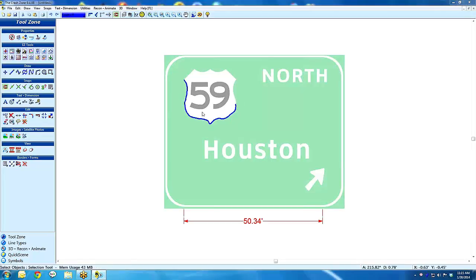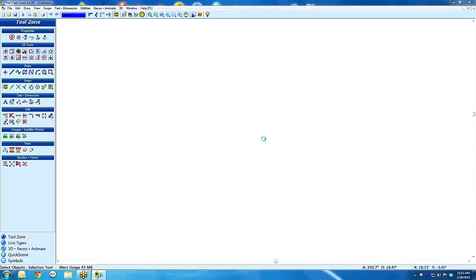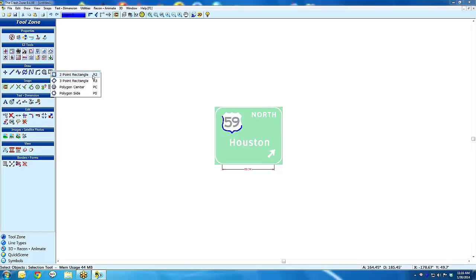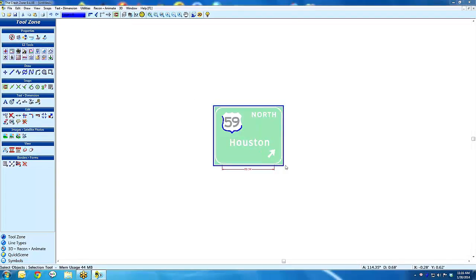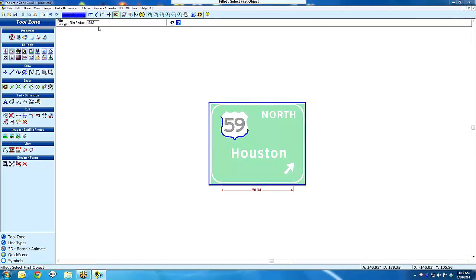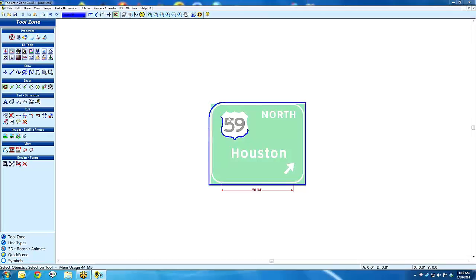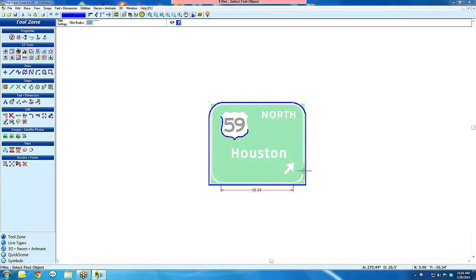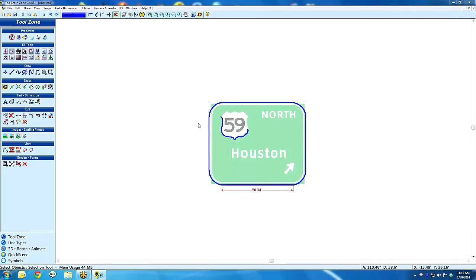There's no way for this to do that. You come in here and you could put your north in and trace it. But yeah, that's exactly what you would do in that case. You have your ortho tools too to do your 90-degree corners if it's a building. Oh yeah, there's a lot of stuff we could do on this too. We could come in here and get a rectangle around it, and then we could grab the fillet tool and set that to 10. Let's see what that looks like. Click here, click there. All kinds of tools we could use. Trim, extend, offset, the whole works.